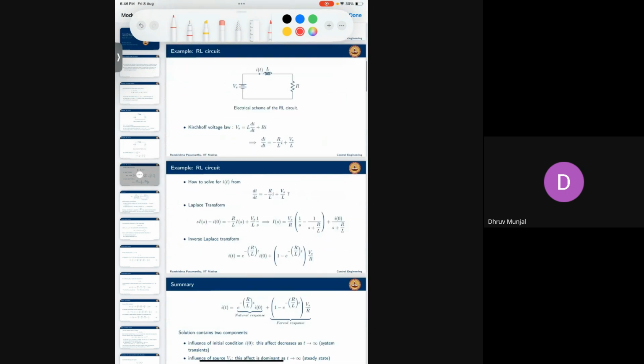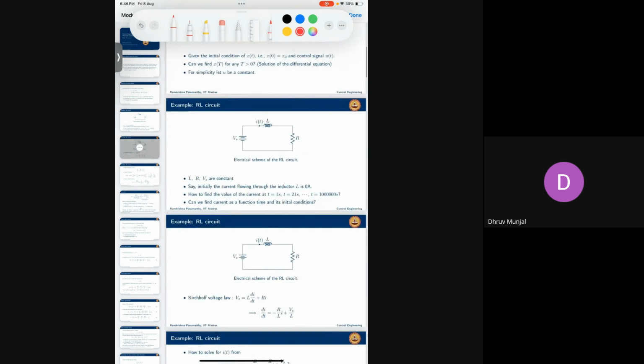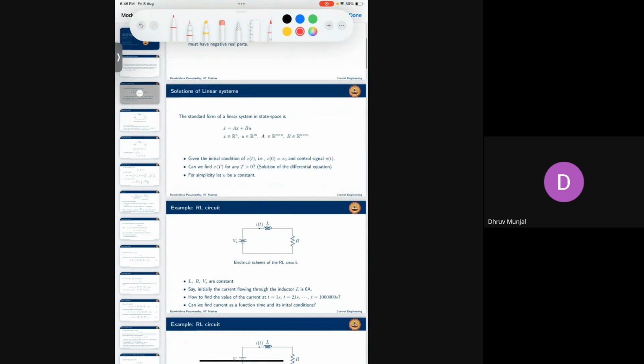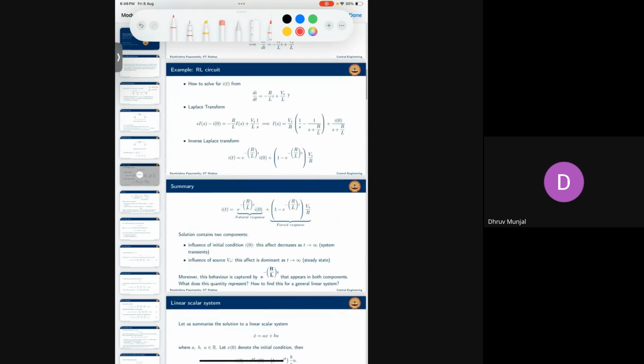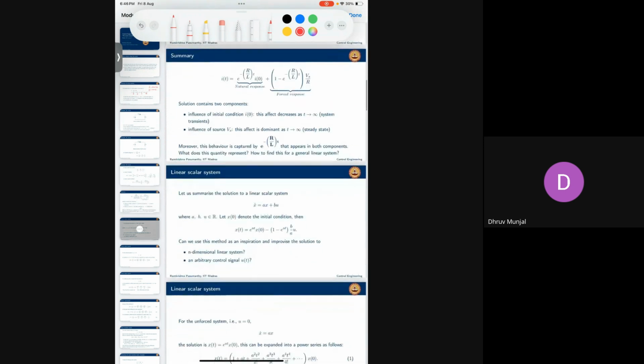This particular slide from here will tell how to find a solution to your linear system. So this is a linear state space representation, Cx plus Du. They have given the dimensions of each and every state matrix so that you can know the dimension of your whole system. So they suggest how you can find the solution to this equation, x of t.